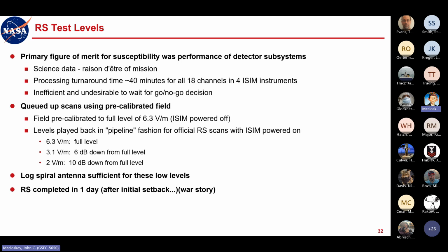The signal was internal to the unit, but you had to run a cable physically from the back panel to the front panel to actually apply it to the signal that you were applying to the EUT. So the signal we were applying was not modulated, and we learned this after about a day and a half of scans. Once we got that sorted, we repeated the scans and finished the test in that one additional day. We did have that setback, which was not fun.